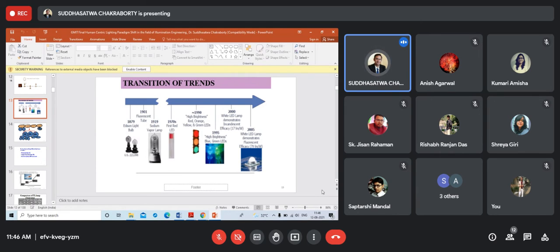Last semester, we talked a lot about the difference between efficiency and efficacy. There is lumen per watt. Here it was a very poor lumen per watt, 17 lumen per watt. So this is a very small value, so it cannot be used like a general purpose source at all. But that's a white LED, and it was a derived LED.